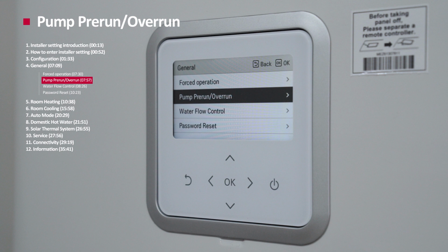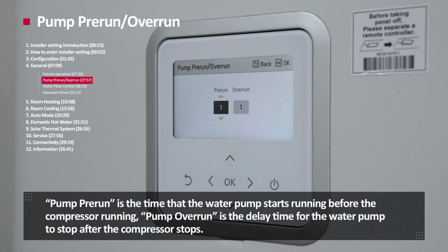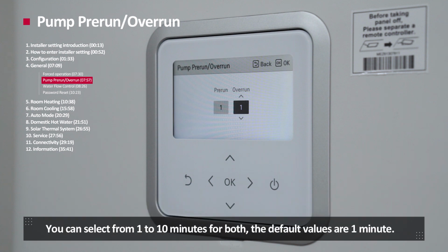Pump prerun, overrun. Pump prerun, overrun sets the delay time of the starting and stopping of the water pump operation. Pump prerun is the time the water pump starts running before the compressor runs. Pump overrun is the delay time for the water pump to stop after the compressor stops. You can select from 1 to 10 minutes for both. The default values are 1 minute.